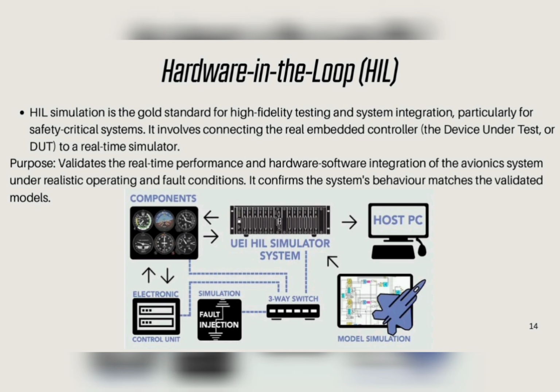Hardware-in-the-loop, HIL. HIL is the gold standard for integration testing. The real avionics hardware, the device under test, is connected to a real-time simulator that emulates sensors, actuators, and the aircraft. HIL validates real-time performance, I/O interfaces, timing determinism, and hardware-software interaction under nominal and fault conditions.